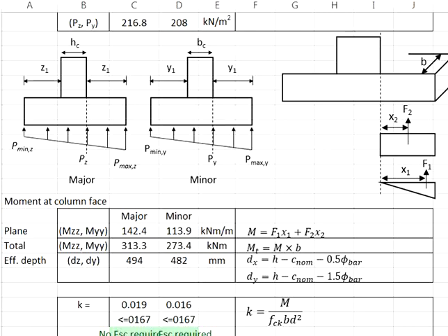If you find difficulty determining the correct B, I would recommend you always sketch and imagine the pad footings in 3 dimensions. Only then can you correctly determine the B. Next, we will need to determine the effective depth of the pad footing. We need this effective depth to calculate the moment resistance given by the reinforcement.